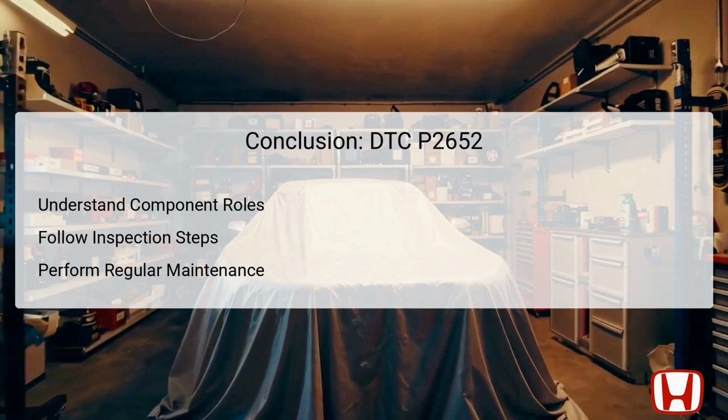In summary, understanding the underlying components related to DTC P2652, such as the rocker arm oil pressure sensor and the rocker arm oil control valve, is vital for accurate diagnosis and repair. Following the methodical inspection and troubleshooting steps outlined is essential for pinpointing the cause of the error and ensuring that repairs are successful. Regular maintenance practices, including monitoring engine oil levels and inspecting VTEC components, can greatly reduce the risk of encountering this DTC again in the future.